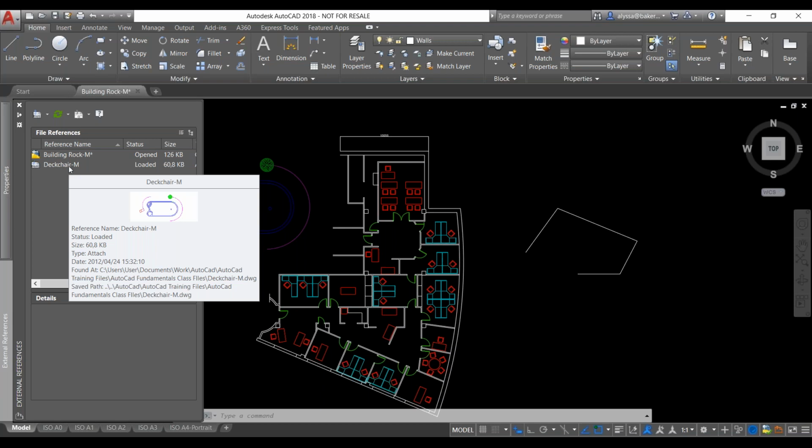The interior department is working on the interior part of the model, and the exterior is being done by the architectural side. These 2 departments can work on 2 different files but link them up together, and that's how you get an XREF. That is called an external reference.